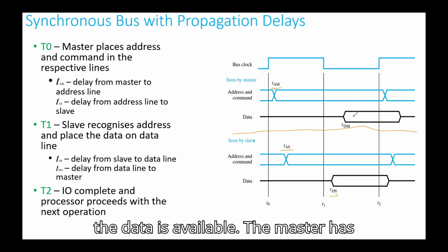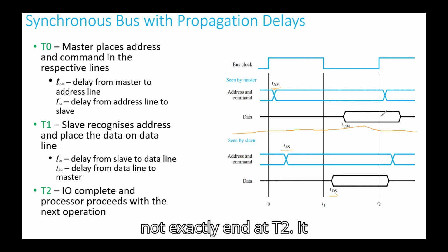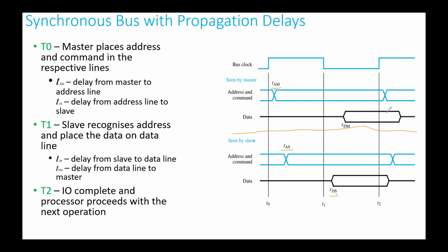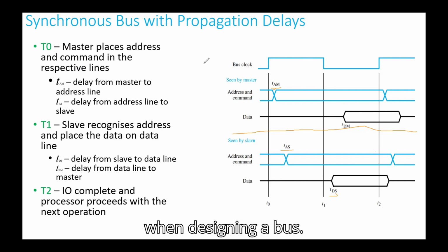Okay, now the data is available. The master has started reading the data and it will not exactly end at T2. It will take some more time to finish the data reading process. So these delays have to be considered when designing a bus.